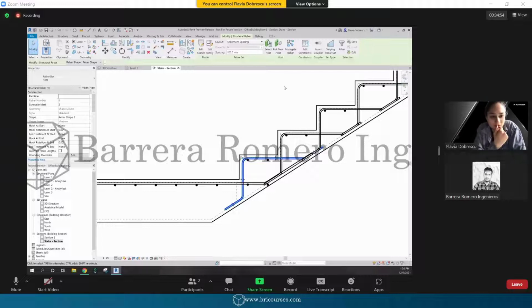So that would be in the properties panel, right? The by-floor mark. In the host, we modeled just like you saw it. We modeled the columns floor by floor. So if I replicate, and the column has a certain floor parameter, and when I use the rebar, sometimes I use shared parameters to make the process a little easier.